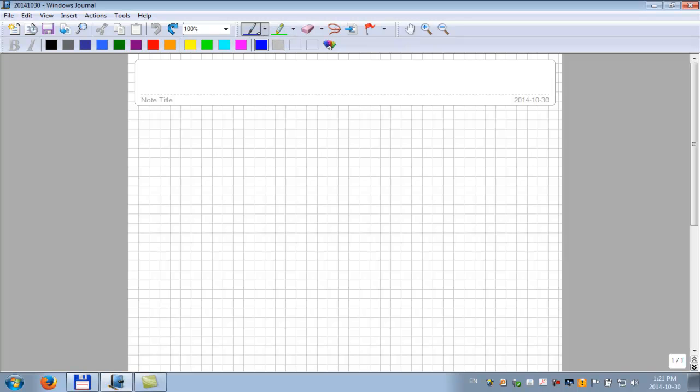And last week, when we talked about the reservoir rate equation, we talked about it for a radial, cylindrical geometry with a wellbore radius, RW, and an external no-flow outer boundary at a distance, RE. And we were talking about, as we will continue next week and the rest of the course, single-phase gas flow. Okay? And we talked about the use of the pseudo pressure function in the reservoir gas rate equation. So I'll just rewrite that equation and we'll start with that.